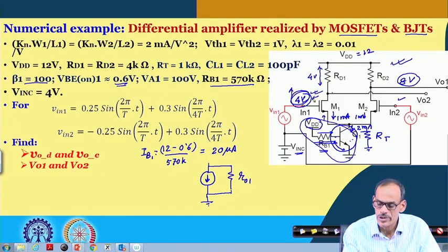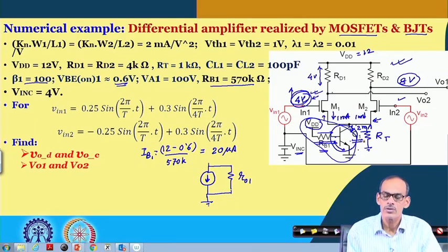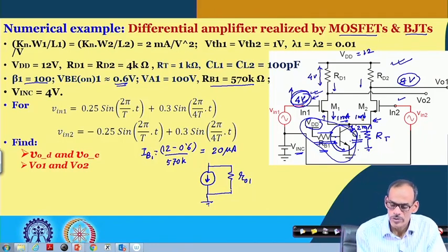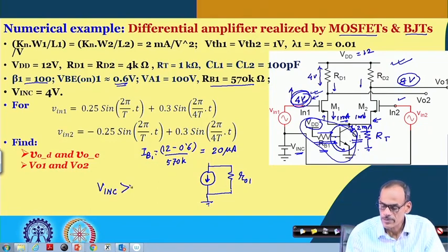are making this voltage very small and forcing the source node very low, pushing this transistor Q1 into saturation. So, as long as that is ensured, then we can say that both this current and this current remain 1 milliampere. And to get that, we can say that V in C, if it is higher than,